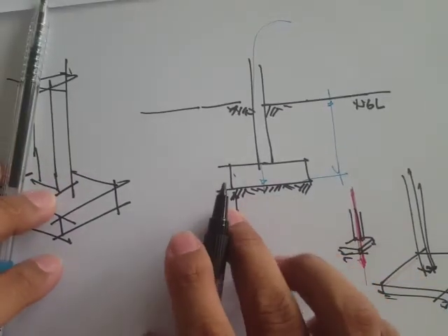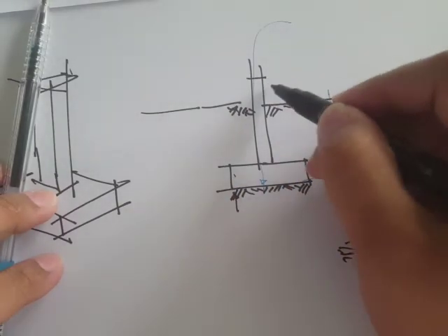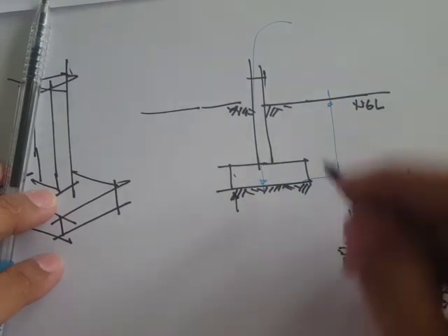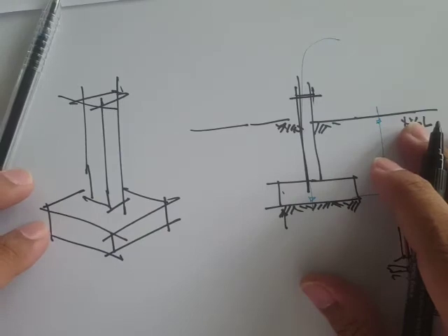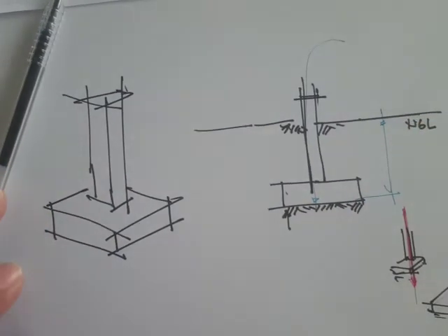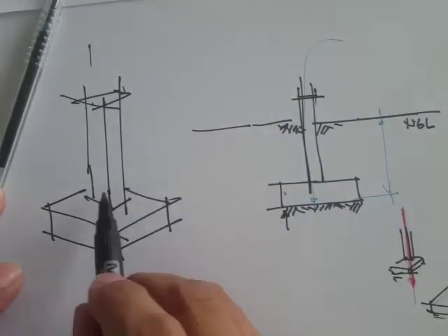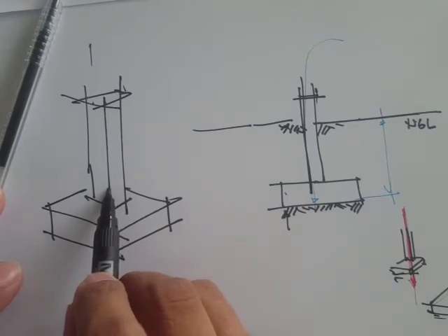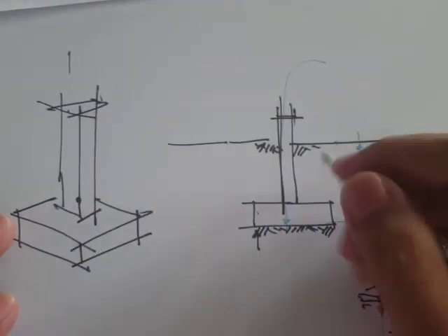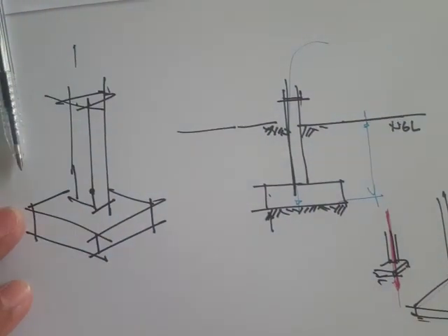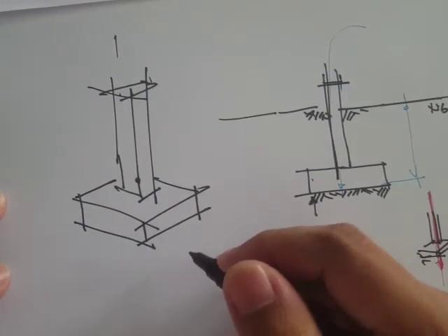Okay, so typical materials for these footings and the columns here is actually reinforced concrete. As I also mentioned, I think in the first video or second video, for steel frame structures, some columns are short enough that they don't need reinforcements, and we call them pedestals. But for longer columns, there's a need to have steel reinforcements.